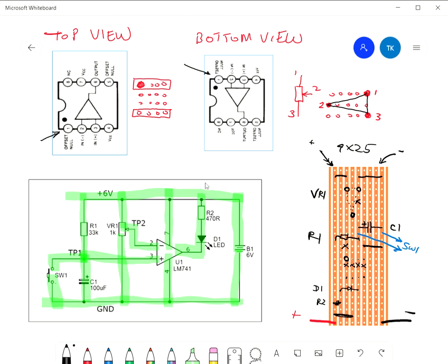When we create our circuit, remember that this view is the bottom side. We will not actually see these components because the components will be going in on the other side. You have to remember that. That's really important. But when you insert it, you will have the leads coming out this way, and then you will solder it, clip it, and that will be the circuit constructed.